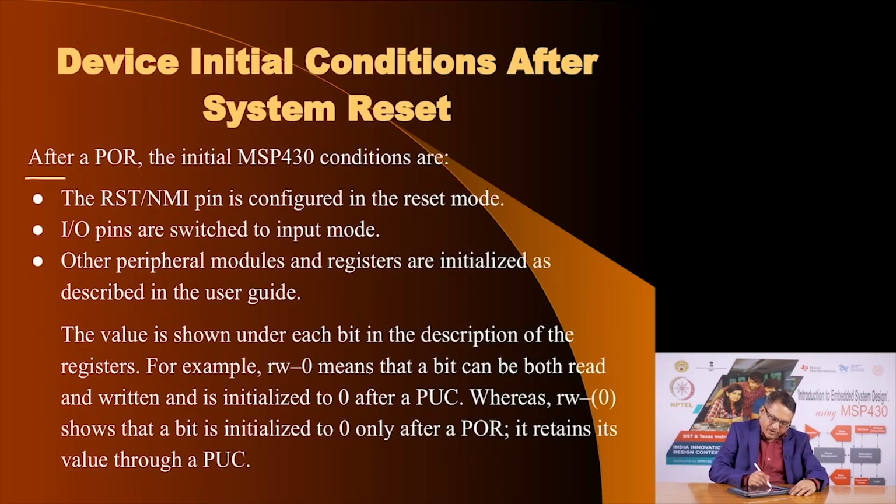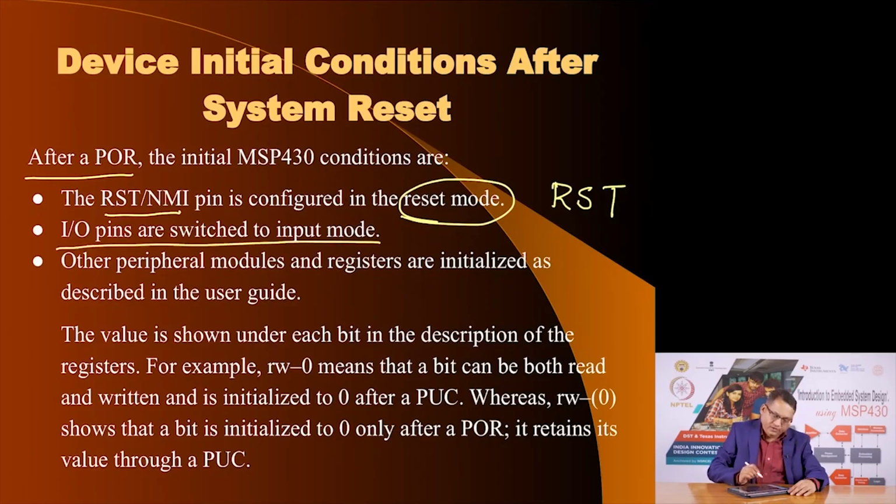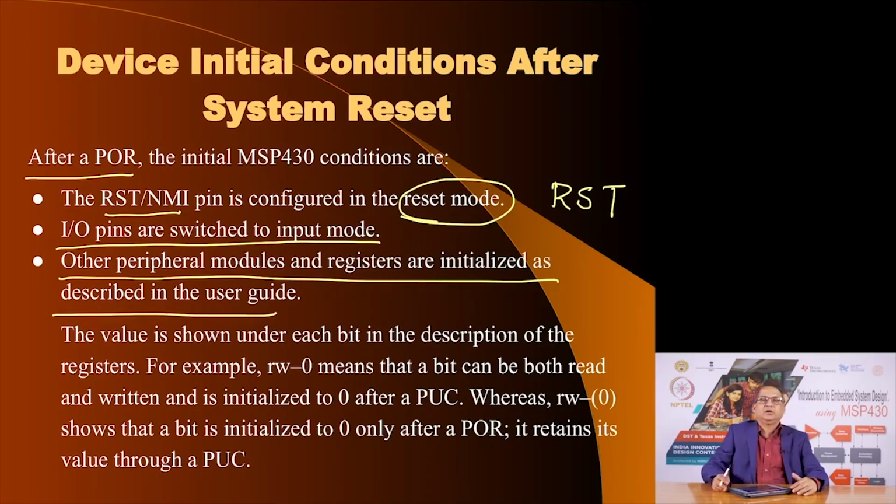After power on reset, the RST NMI pin is in the reset mode, that is, it works as RST pin, not NMI pin. The IO pins are all switched to input mode, and other peripheral modules and registers are initialized to a known value, which you should refer to the data sheet and the user guide for exact information. Now, this is what I had mentioned earlier. Each of the registers, when it is reset or when it is cleared, meaning when it is POR or PUC,